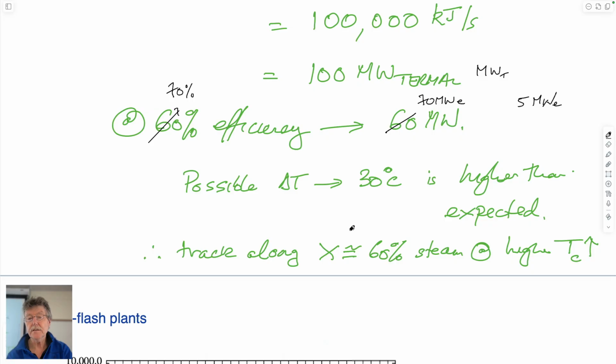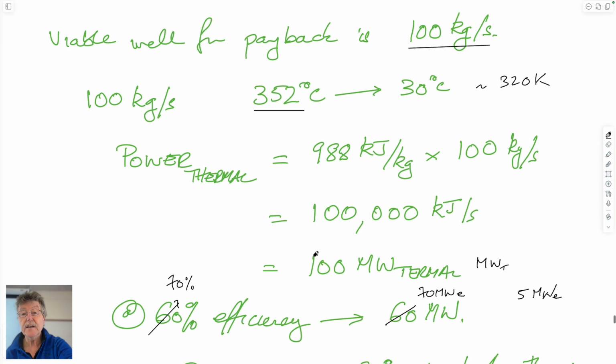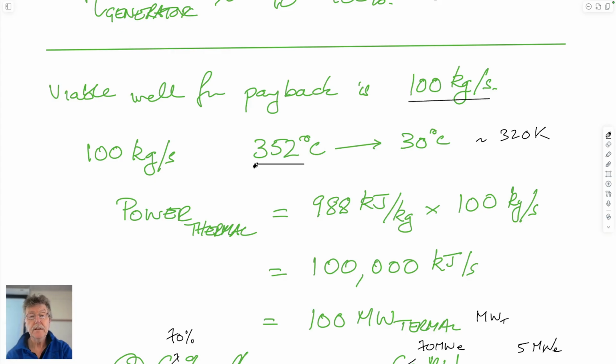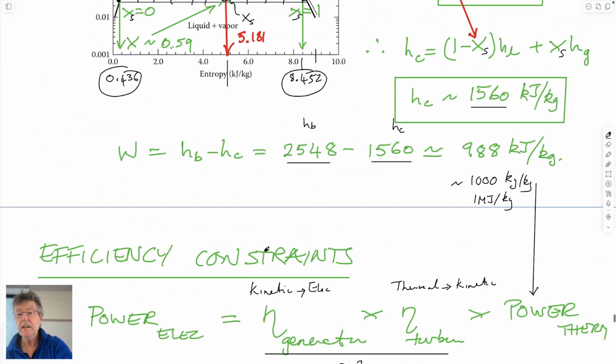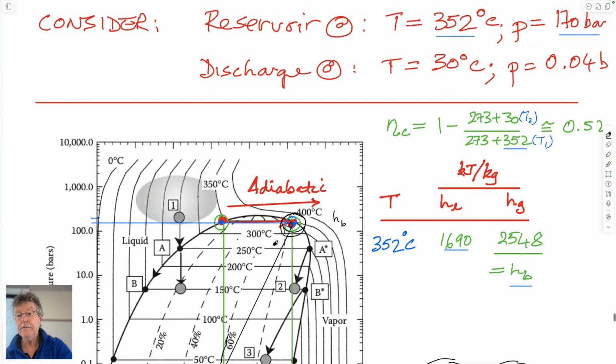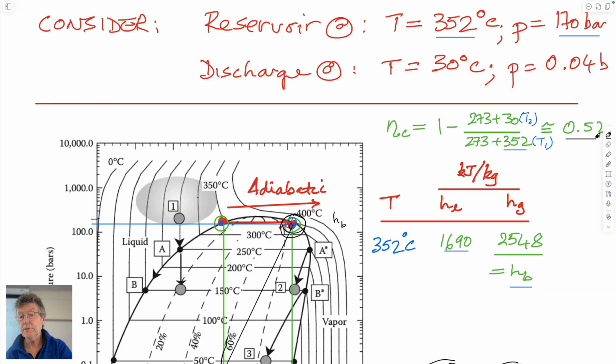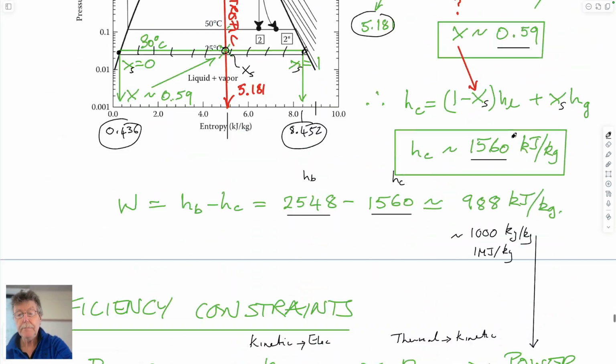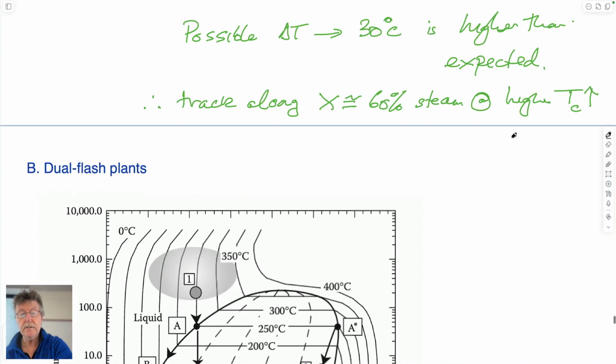And the reason is because it's a huge drop in behavior, because it starts out at very high temperatures. And so the net result of that is there's a big temperature drop, and therefore the efficiency of the system greatly increases as we go to higher temperatures. And that's reflected in this much larger value of efficiency that we get as we have a larger temperature drop between recovery temperature from the reservoir and background temperature as we pull it out into the subsurface.